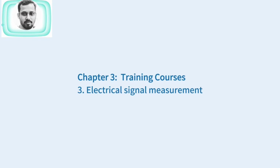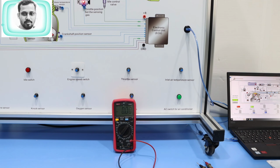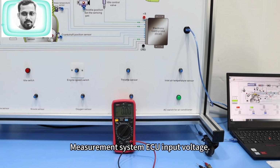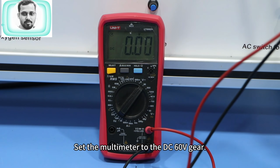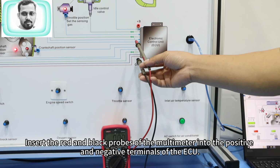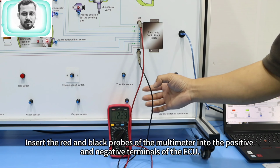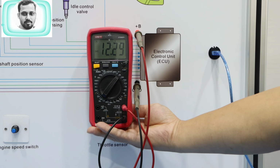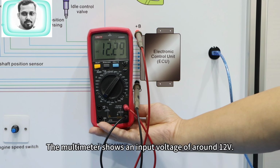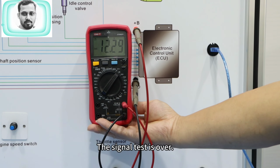3. Electrical signal measurement. Next, we will conduct signal testing. Measure the system ECU input voltage. Set the multimeter to the DC 60 volts gear. Insert the red and black probes of the multimeter into the positive and negative terminals of the ECU. The multimeter shows an input voltage of around 12 volts. The signal test is over.